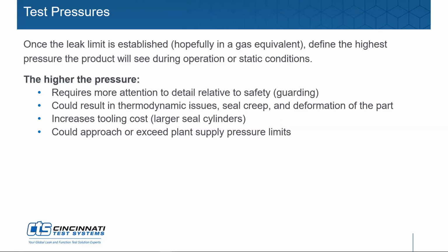You're also going to see thermodynamic issues creep in, and that's associated with compressed gas. When you compress gas, it heats up, and as you increase your pressure, there's a thermal event that you need to stabilize to dissipate that temperature rise immediately after pressurization. Seal creep and deforming your part are two other areas associated with increased pressure. So make sure you've accommodated larger seal cylinders on your test system to handle the force that will be applied to that surface area.